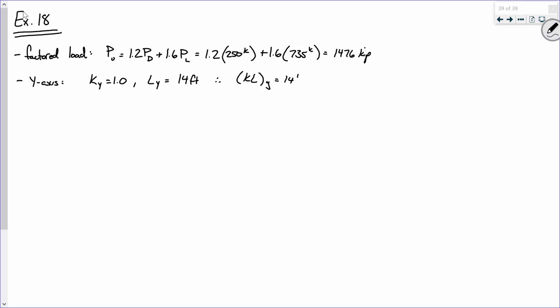Now here's what we're going to do. We're going to go into the manual, to Table 4.1. You remember how this works, right? We start at the W14s and find the lightest shape that we can find. We're going to do things a little differently. I wanted you all to get some experience with the manual before I show you what I am about to show you. It's just something that you want to keep your eye out for when you're selecting shapes.